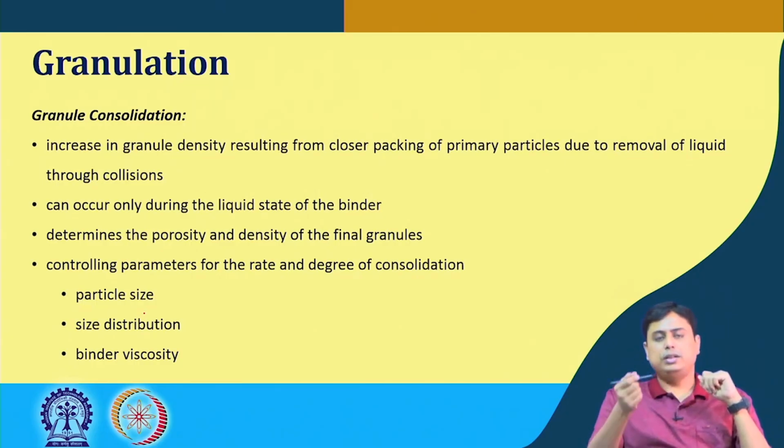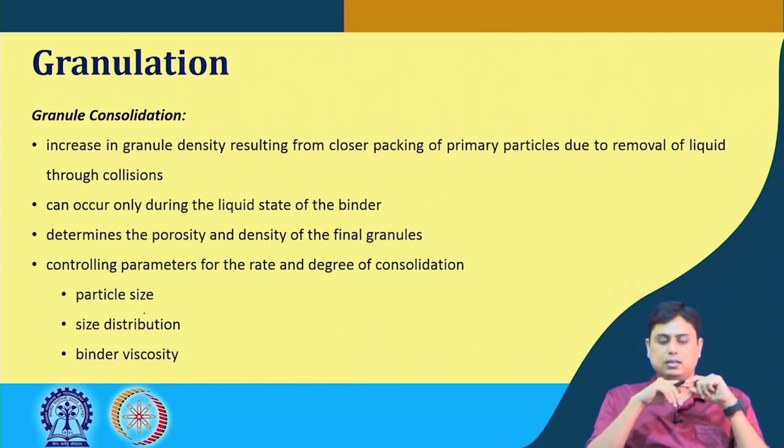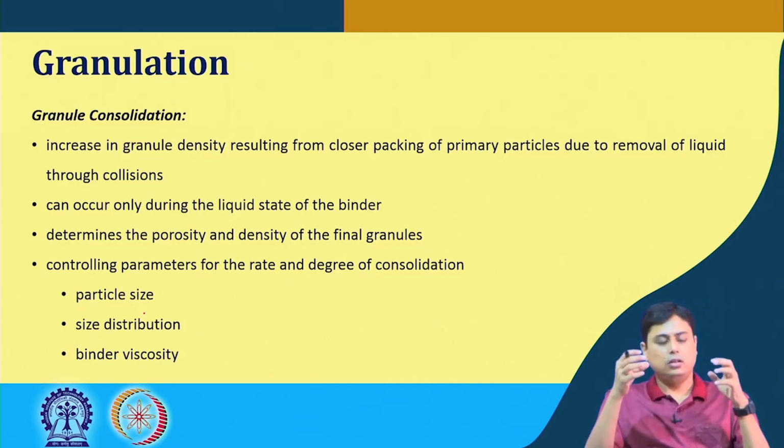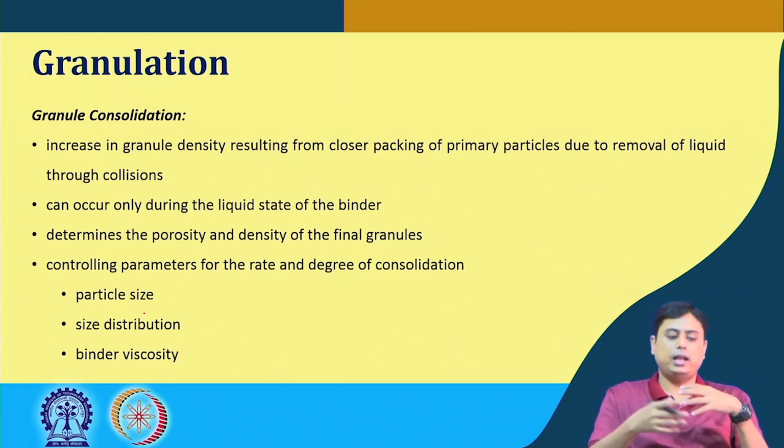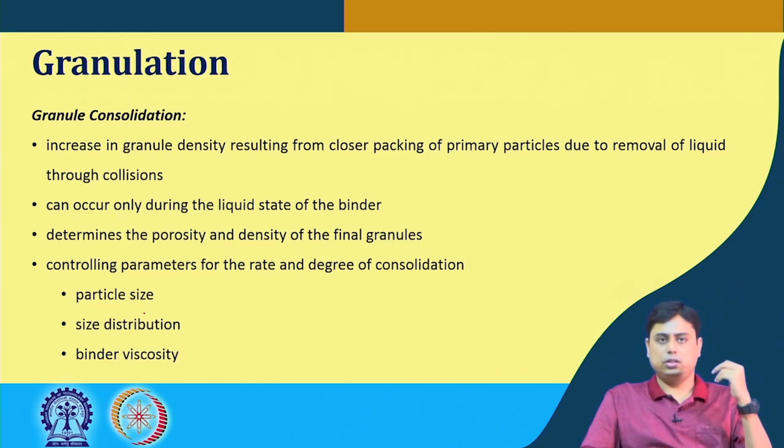But this consolidation rate and its degree is controlled by particle size, size distribution, and the binder viscosity. So, the involved granule, its size, its distribution, and the binder viscosity dictate the rate of consolidation and the degree of consolidation.